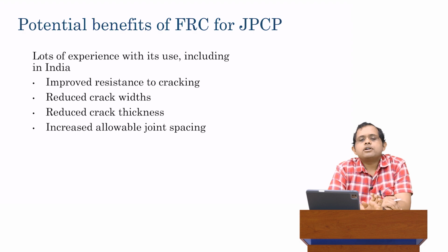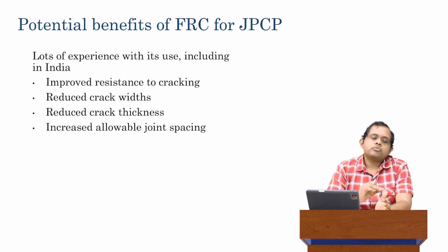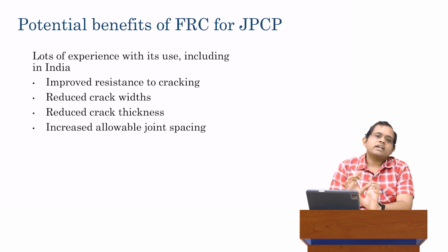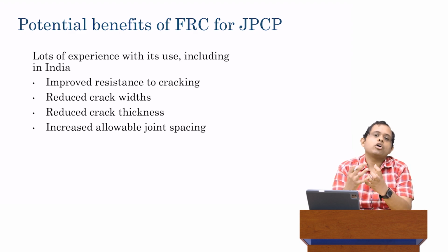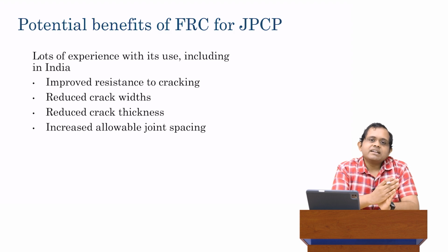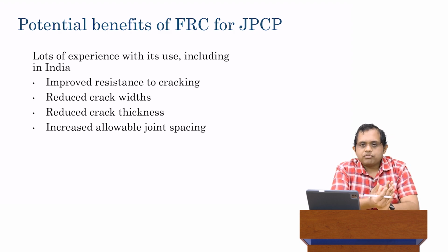In general, in rigid pavements, we tend to use microfibers. The reason for that is quite simple. It's because they are much easier to mix together. Macrofibers, because they're so long, have a tendency to get bunched up or balled together, particularly around coarse aggregates. So it's a little bit difficult to mix macrofibers into concrete to create FRC.